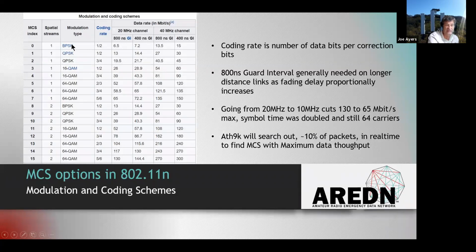So it's relatively easy. We need the lowest signal to noise ratio to detect that carrier wave in two states. Here it is in 4 states, and then we jump up to a 16 state signal, also starting to use the amplitude of it, and then 64 states. And that's all in one polarization.